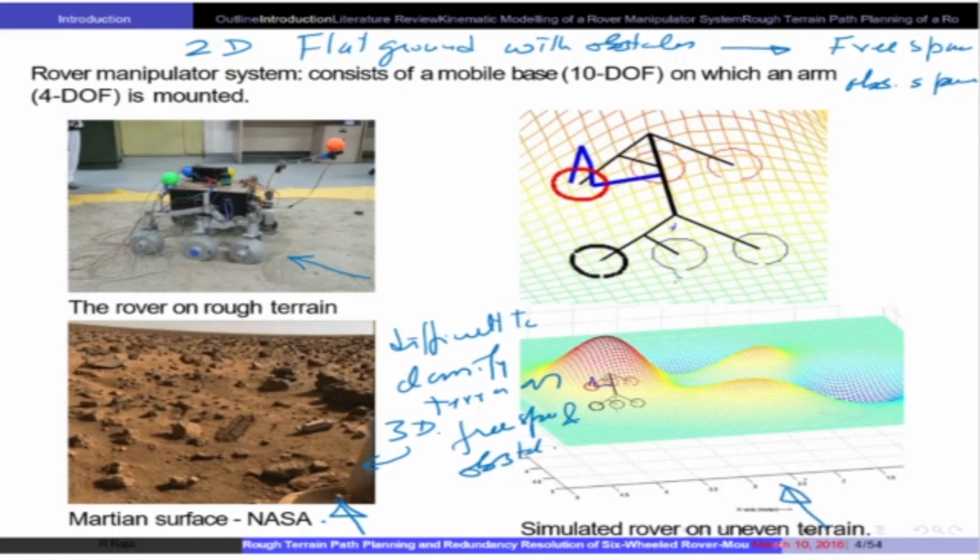side picture. Suppose you say that this is a very steep gradient there. Okay, so I'm talking about a gradient now. There's a very steep gradient there. Now the robot obviously cannot climb that. It can become unstable, it can topple over. Now that is an obstacle. Let's say a very high gradient is an obstacle. Okay, so that I can classify and say this is an obstacle.